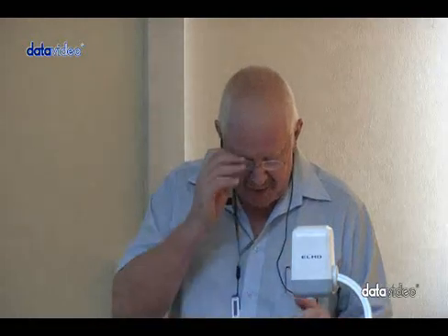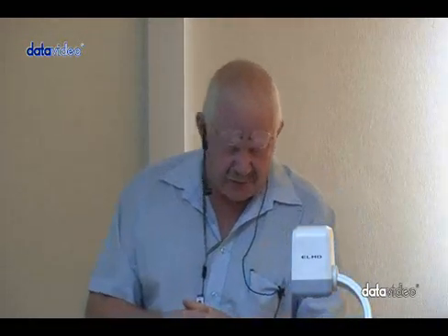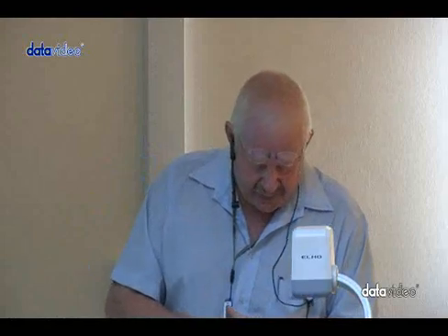So if I go and have a look at example 6.2, where they use this formula in an example, determine the r'e of a transistor that is operating with a DC emitter current of 2 milliamps. So the 2 milliamps has already been calculated. I just put 2 milliamps into this formula. I get a value in this specific case of 12.5 ohms, which brings me to the next point. Please note that the value of r'e is quite small. It's normally between, I would say, 5 to 20 ohms. So if you calculate the value of r'e and you get a value larger than that, you must know that you've made a mistake somewhere. So that's one way to check your answers, to know what type of answer you expect.